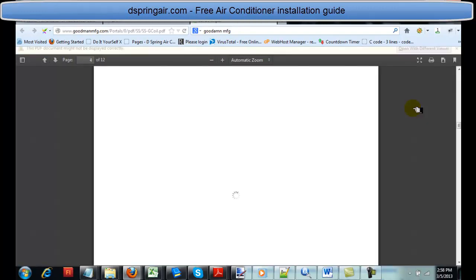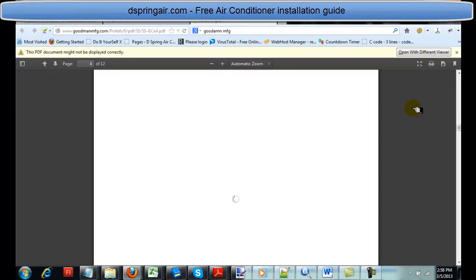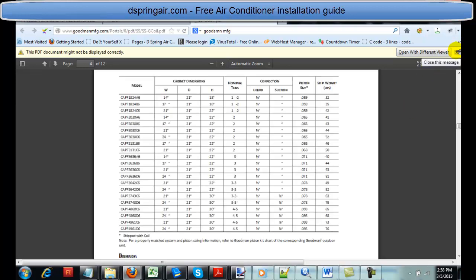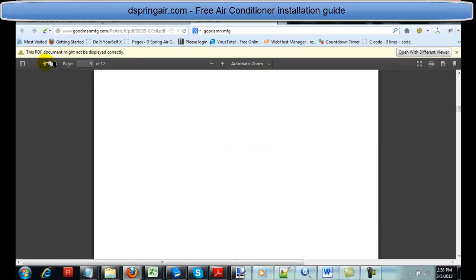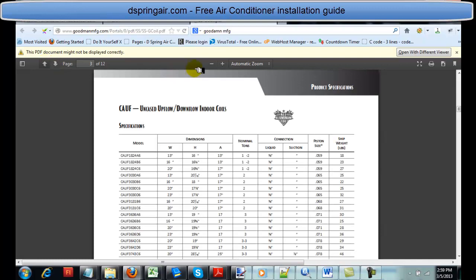Now, if you're going with a Goodman furnace and a Goodman coil, you just get the model and the serial numbers, and you call up Goodman or Johnstone or somebody in your area who carries Goodman, and you say, hey, what size coil do I need for this unit? And they'll just tell you, oh, you got a 2 ton, that thing will handle 2.5 ton, and here's the sizes. But if you're mixing and matching yourself, you have to combine a couple things.